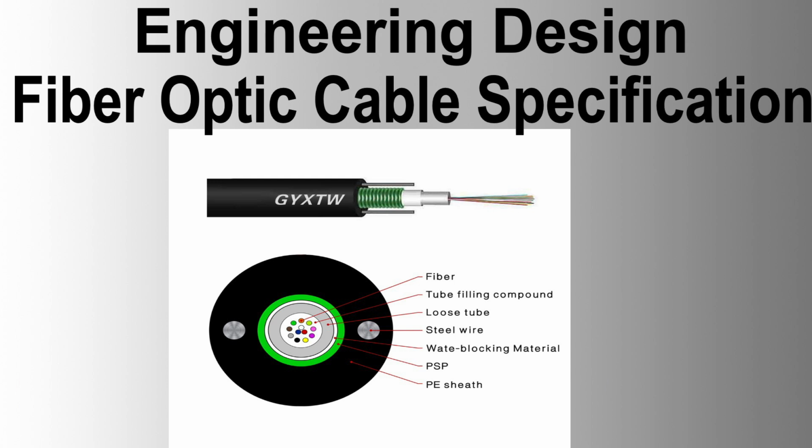Routing plan preparation. Prior to conduit installation, the contractor shall prepare a routing plan used in conjunction with the approved pipeline alignment sheets and drawings. This plan will list manhole locations, splicing chambers, conduit installation types, e.g. open cut road, wadi crossings, road crossings, and HDD, and conduit coupling locations.